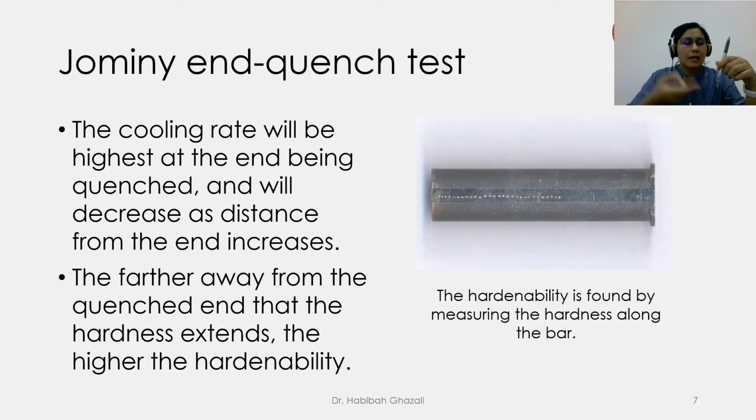Logically, the cooling rate will be highest at the end where the water touches, and this cooling rate slowly decreases as the distance from that end increases. After the test, they took out the specimen and used hardness tests to find the hardness at various distances from where it was quenched. We know that the cooling rate is different at different distances.